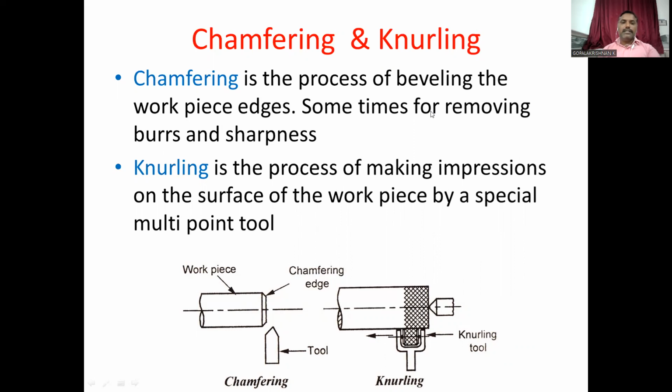And one more operation in the lathe, knurling. Knurling is the process of making impressions on the surface of the workpiece by a special multi-point tool. Here in this drawing, the chamfering and knurling tool is given.